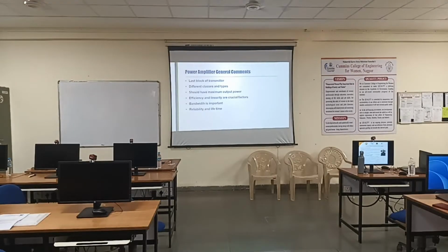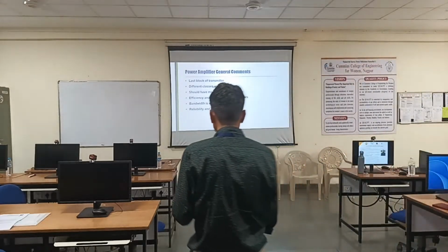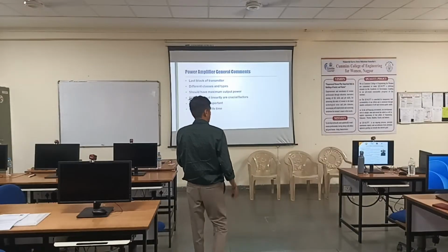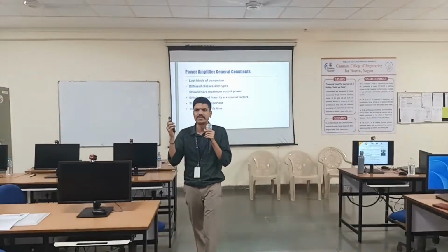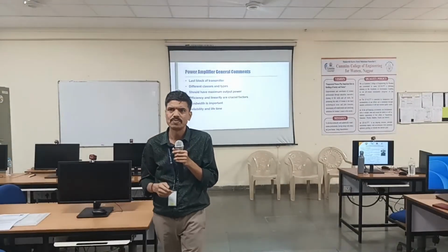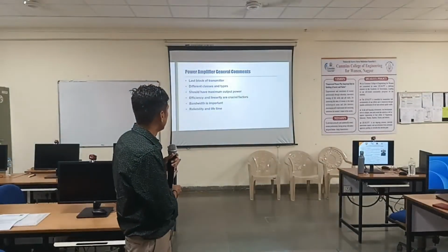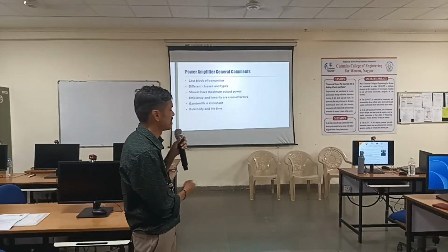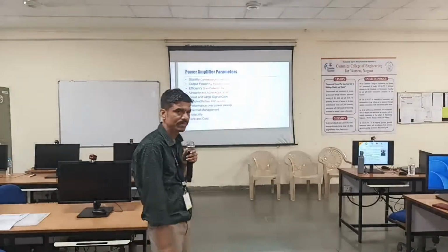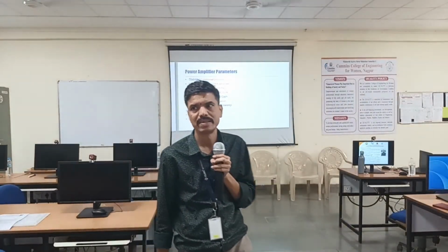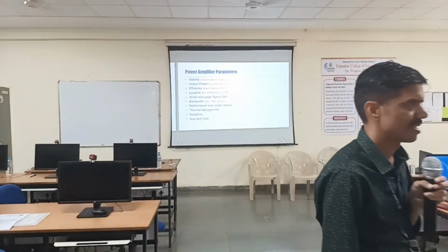Now these are some of the general comments which we have discussed. You can just go through this. Here is the last block. There are different classes: class A, B, AB, E, F, S, D, J, inverse J, whatever you name. More than 10 classes you will find. Then it should have maximum output power; efficiency and linearity are crucial factors. Bandwidth is important, and reliability and lifetime also need to be considered for PAs. Let's start the PA design.